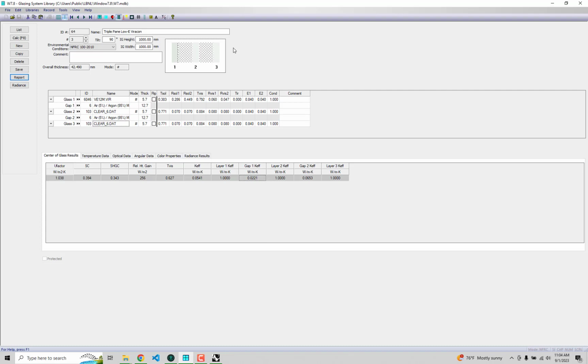In my practice, when I worked at Payette, we tended to use triple pane as a basis of design, mostly because we had found that we could make a cost-effective argument for triple pane by showing that using such an insulated piece of glass, we could actually remove the perimeter heat and cut down overall costs. So almost on all the projects that we were doing, at least at the time when I moved to working full-time on Ladybug a few years ago, all of our projects were pretty much assuming triple pane in Boston, but with code baseline assumptions for everything else. So this is what we're going to create here.